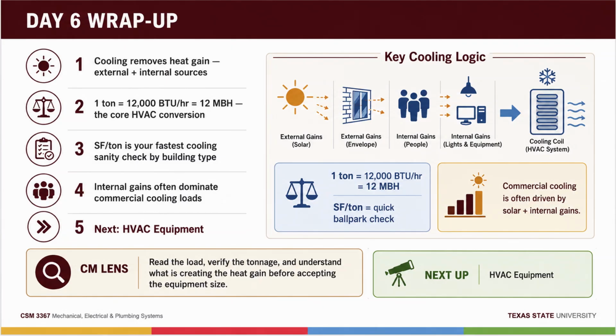Step 2. Total it, split it. Total BTUs per hour, and the sensible/latent split, 2 subtotals. If your latent line is 0, you skip the people and the outdoor air moisture, and that's the number 1 error on this assignment every semester. Step 3. Convert to tons. Total over 12,000. Round sensibly and say what nominal size you'd carry. Step 4. Sanity check. Square feet divided by tons, compared against the rule of thumb range, with 1 sentence on whether your answer is reasonable and why.